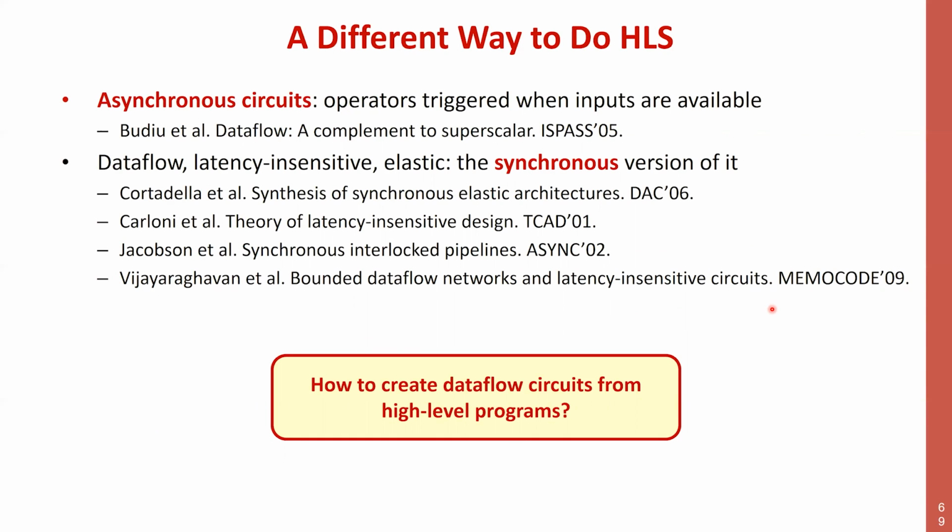Practically no circuit exists in practice that really does this. And this is the category of asynchronous circuits. Circuits where you remove the idea of this clock that is distributed to all the components, but you simply have, when something is ready, it is memorized in the next register, and everything is done by checking readiness and advancing on readiness.